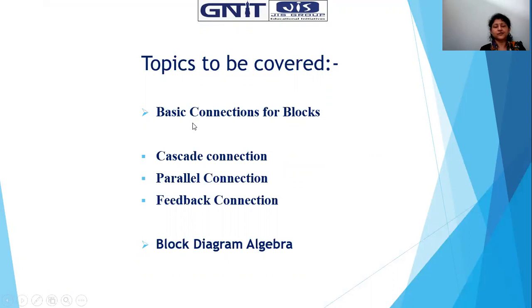Moving to the topics, what are the topics to be covered today? That is basic connections for the blocks. Individually, what connections are possible in a block diagram will be discussed, and those connections are mainly cascade connection, parallel connection, and feedback connection. As well as the algebraic manipulations used to reduce the block diagram. Before going to the reduction technique, we have to go through the algebra involved.